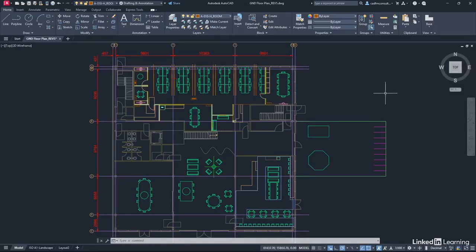That's why you use those by layer settings, because you've got hundreds of objects that may need a color change, a line type change, a line weight change, and so on. Now, that's the benefit of this particular tool. The properties of an object can be individual, or they can be set to the properties of the layer that they are on.